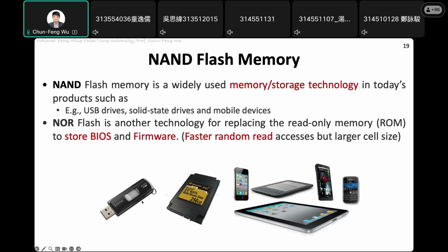Usually inside this kind of device, you will need extra ECC to make sure your reads and writes are correct, so you will take extra time. This is the reason why different devices, even using the same NAND flash, have different quality, and you need extra strategies to deal with the errors.